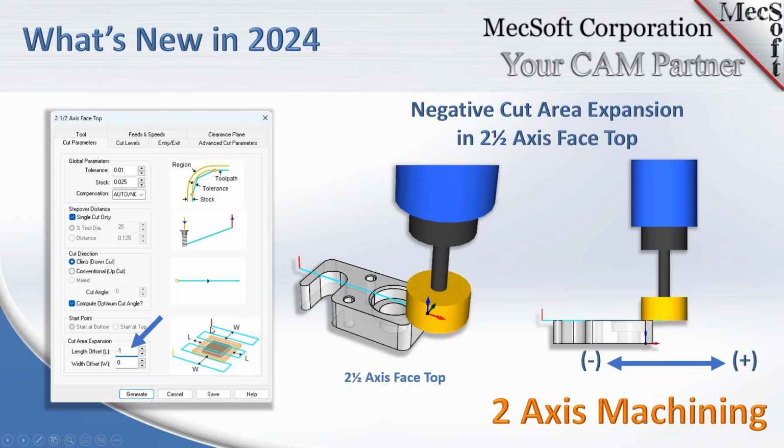If you look at the icon right here in the dialog, what this operation does is it adds distances to the maximum size of the part in the stock. Previously you could only add distance to the tool path, move it out, but you could never move it in. So now you can enter a negative value here, and that'll tighten up your tool paths and save you a little bit of time.